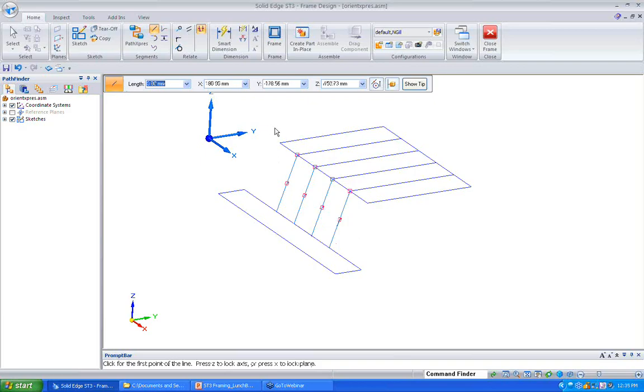Now in this case, what I'm going to do is select the axis instead of the plane. I just select the point, and instead of clicking on the plane, I select the axis. That will restrict the sketch to the Z axis. In this case, I want to go down, and the extent will be defined by the sketch. Now in order to move left, I will just select the Y axis and then give it an extent. Similarly, I can get the same sketch here by defining the axis and the extent.